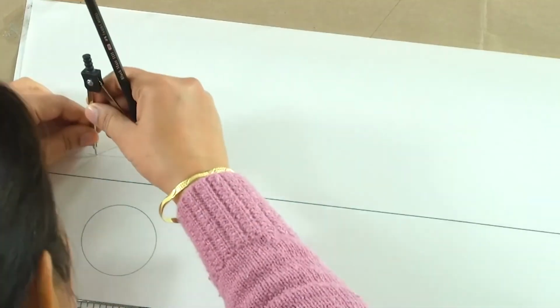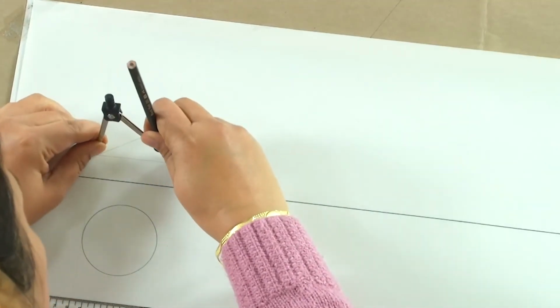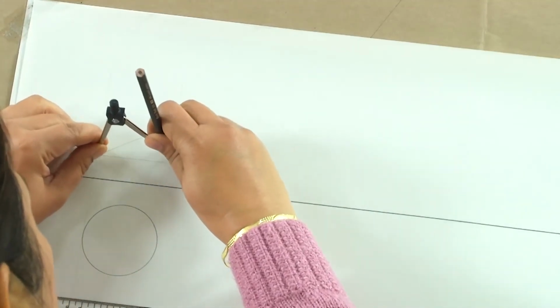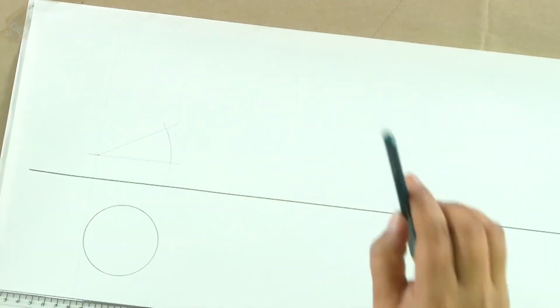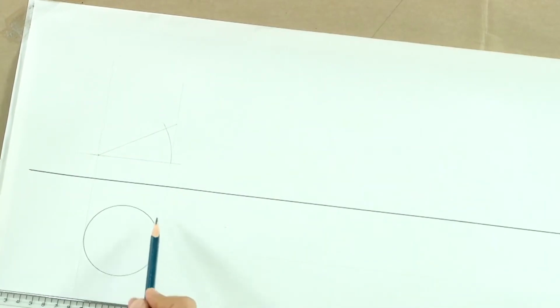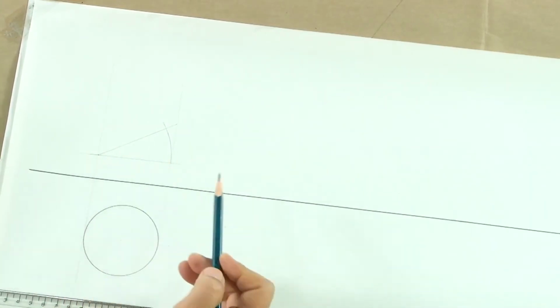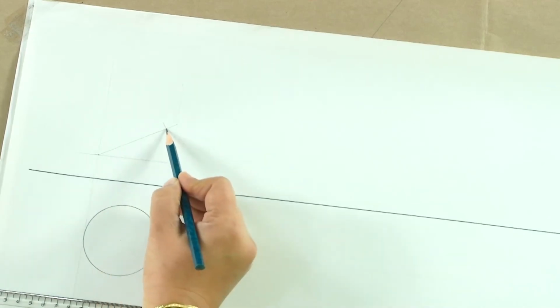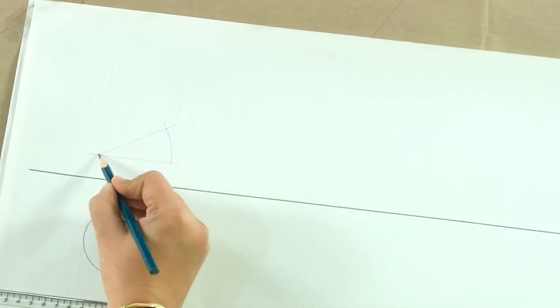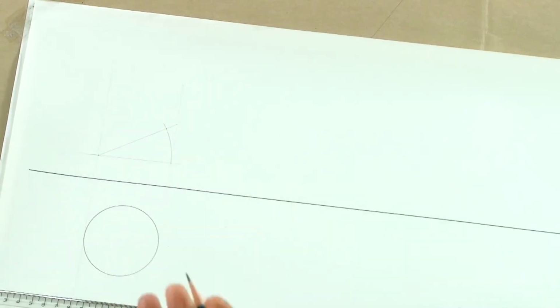So, what will we have? We will have the same circle inclined at 30 degree, and this is what we will have. So, what we do? We make the circle its true shape parallel to HP first and perpendicular to VP, and then we incline it by 30 degrees, which is the final trace of this circle. Now, we have to bring it back. How do we do that?